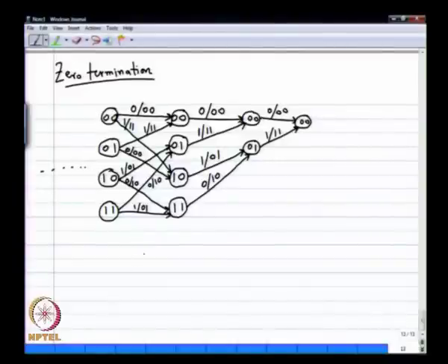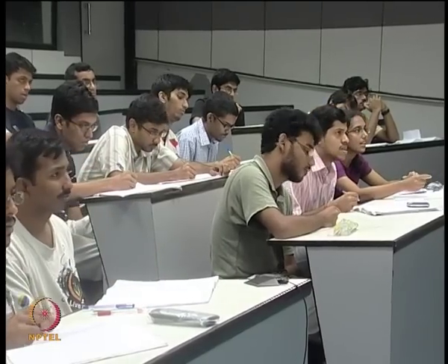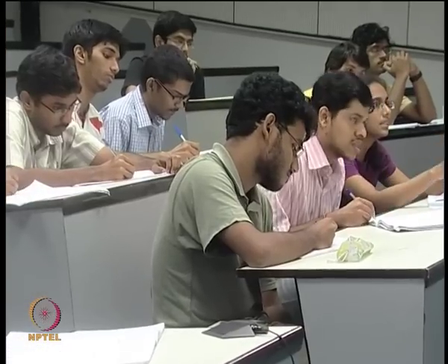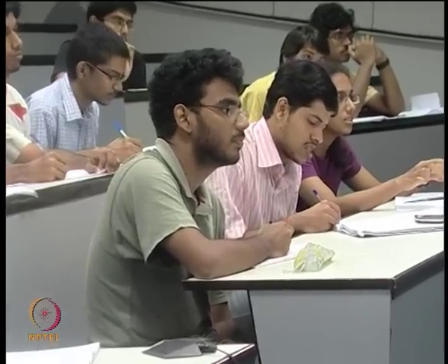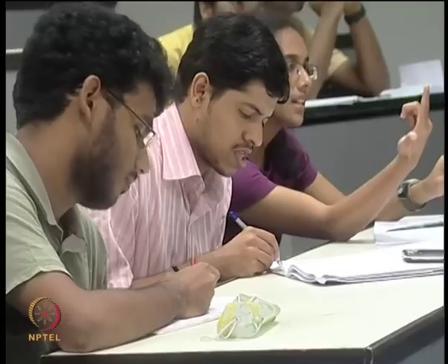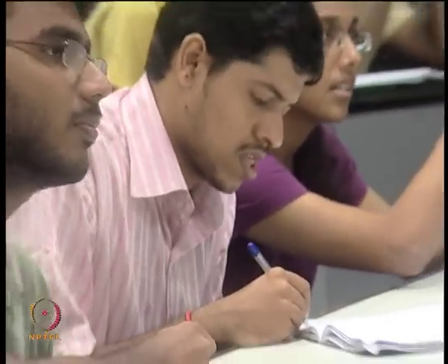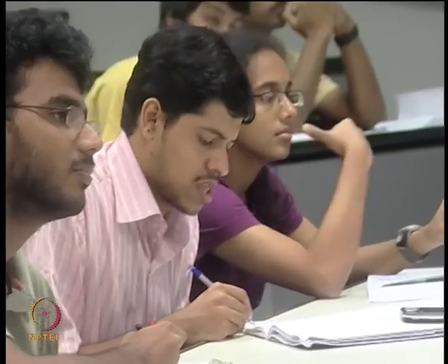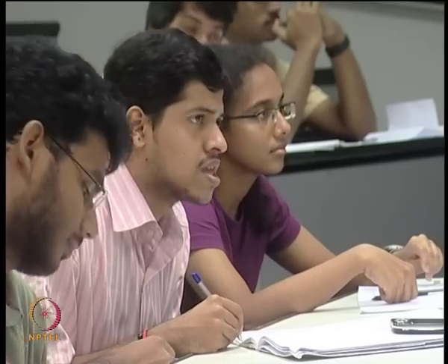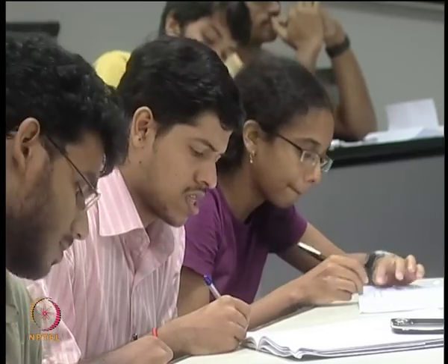This is last stage, and then you do the termination. So, but in the previous case, I had an input, I just appended it with all zeros and sent it. Now, depending on the message bit, I could have been in any of these states. Yeah, that's right. So, does that mean that only when I know which state I am in? Yeah, so you can't figure out the bits you have to append ahead of time. You keep clocking it out, and when you come to the last bit you know the state, then based on the state you can do it, it is not a problem.